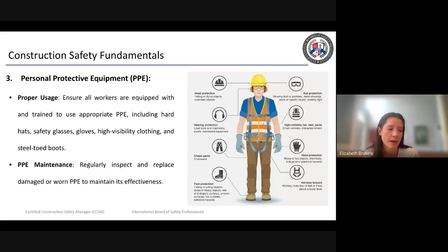So if your construction site requires that you and your workers utilize personal protective equipment, then you need to make sure that you also have a schedule for maintaining the PPE, ensuring that workers are trained on the proper use of the PPE and that they're regularly inspecting it and understand when they need to replace damaged or worn PPE to ensure that it's being as effective as possible.